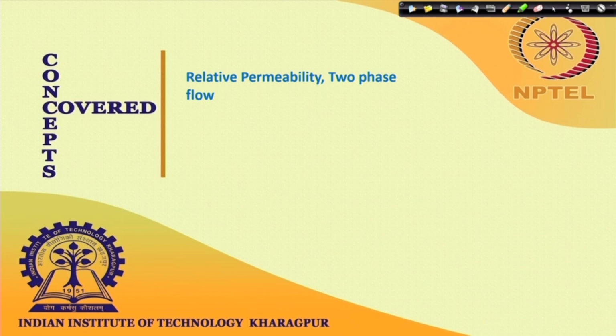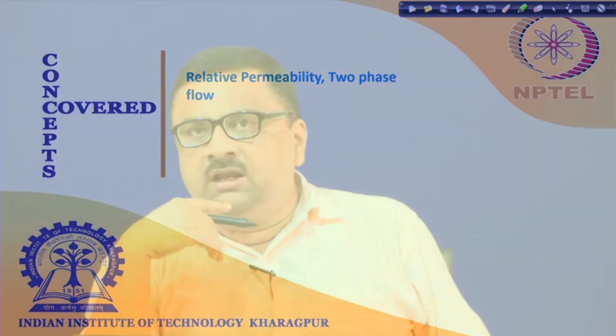Welcome to this lecture of flow through porous media. We were discussing immiscible flow of two phases, and in this connection we had talked about relative permeability and two phase flow. Now, what we were discussing in the last lecture was this Buckley-Leverett formulation, and we had particularly discussed a porous medium containing wetting and non-wetting phase, with the wetting phase at interstitial saturation. So it is primarily non-wetting phase.